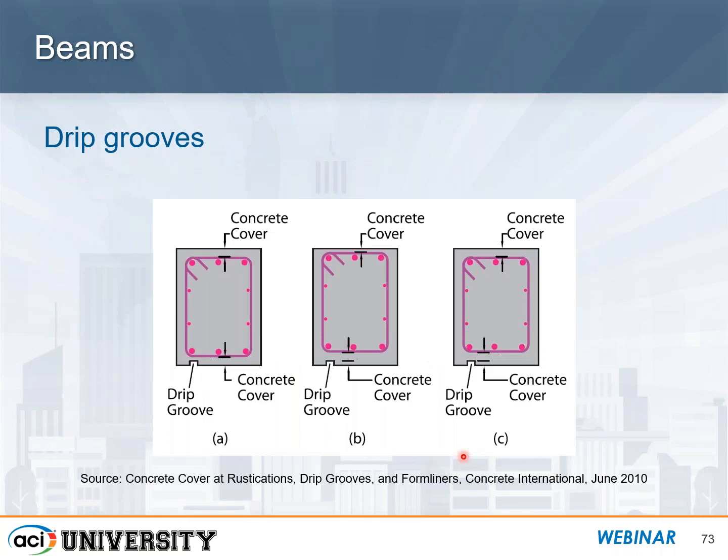Okay, drip grooves with beams. Again, hopefully this information is provided prior to construction. Otherwise, you're going to have a cover issue. So our best bet is, if we know we have a drip groove, just size the beam and reinforcement and such, considering the additional cover that's needed because of that drip groove.